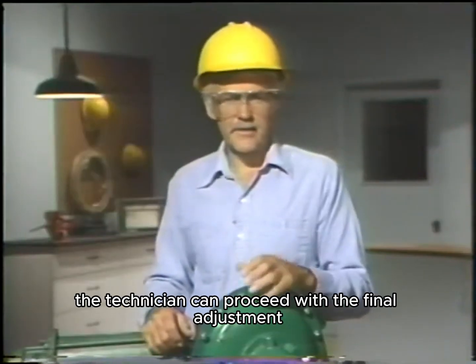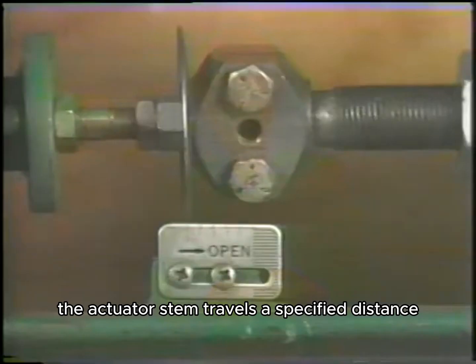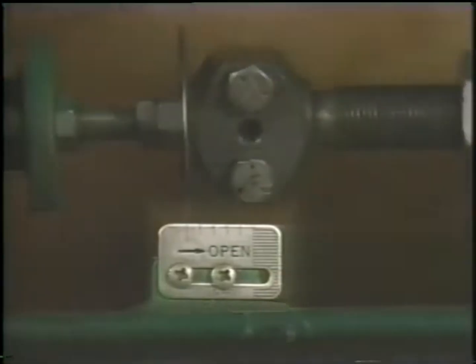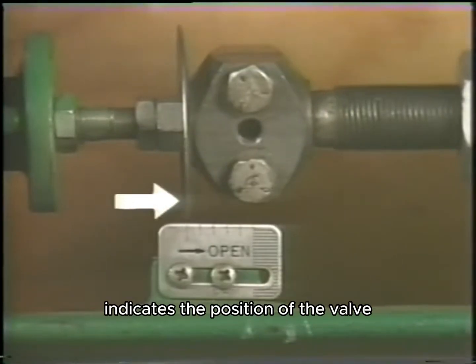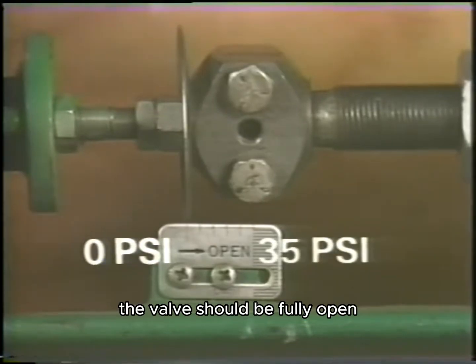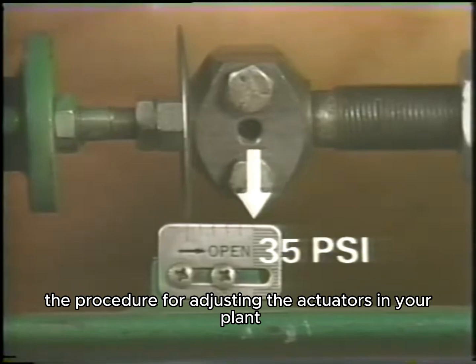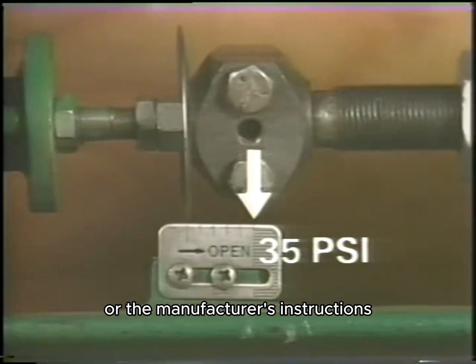There aren't any leaks, and so the technician can proceed with the final adjustment. Basically, he'll be adjusting the spring tension, so when a given pressure is applied, the actuator stem travels a specified distance. The amount of travel is determined by looking at this position indicator plate next to the stem. The position of this disc on the stem, in relation to the scale, indicates the position of the valve. At 0 psi, the valve should be fully closed. At 35 psi, the valve should be fully open. For our demonstration, the technician will be adjusting this extreme. However, the procedure for adjusting the actuators in your plant may be different, and so make sure to refer to your plant's procedures or the manufacturer's instructions.